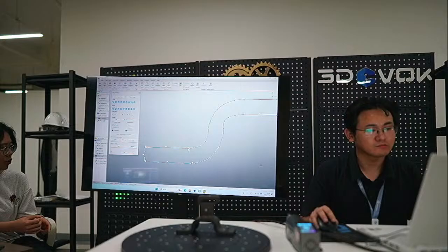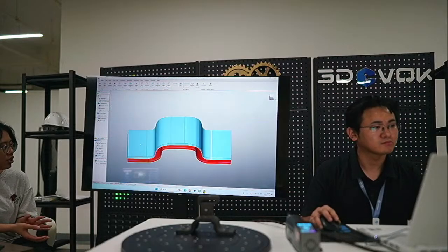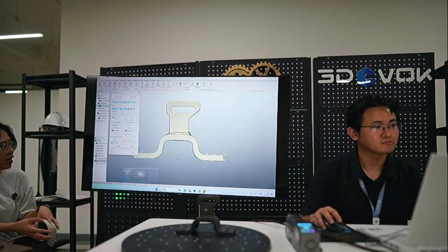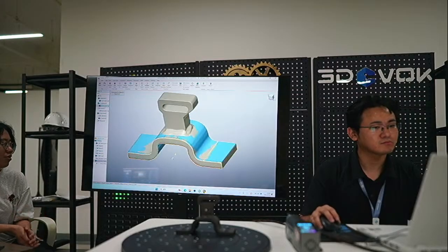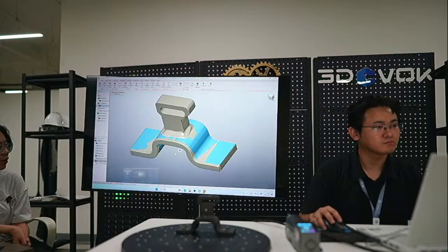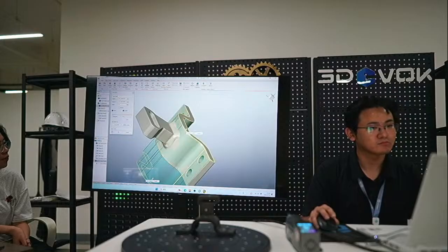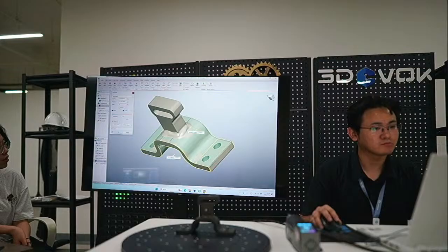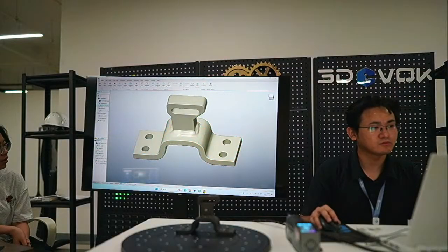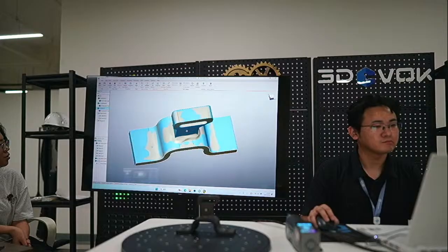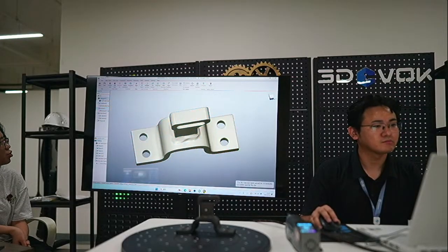In this case, we can also return to the 2D sketch stage to subtly adjust some points on the sketch, so that we can make this extrusion fit the actual surface better. So after the adjustment, we can combine the two solids together.